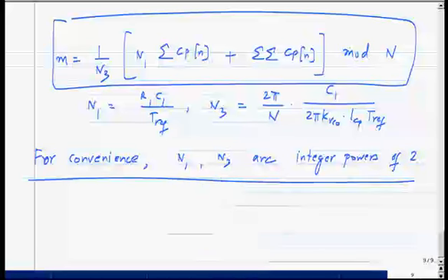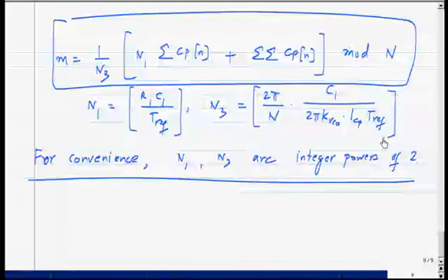So for the assignment in the self-study course, you first compute the values that correspond to your analog clock and data recovery circuit and implement that. You take the nearest integers corresponding to these constants. Oh, by the way, these have to be the integers corresponding to these numbers. Okay, so you take the nearest integers and then you go one first step further and then approximate them by the nearest power of 2 and then see how the CDR behaves. Okay.